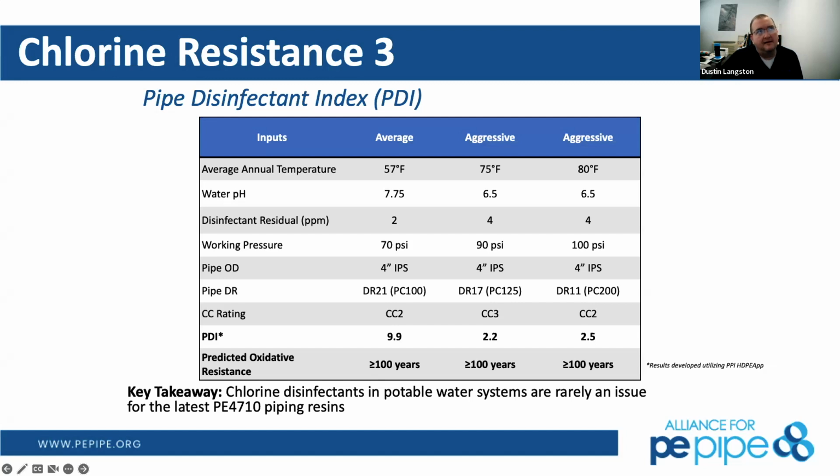So about 5-8 years ago, we were having tubing size failures from high temperature and high chlorine concentrations in the Southwest desert. So Tucson, Arizona, Las Vegas, Nevada, and all of these were on tubing for water service sizes. Mostly 1-inch DR11, 3/4-inch DR11, very thin pipe walls. And we were seeing these failures as soon as 15 to 25 years after installation. And looking at those failures and what the failure method was, which was ultimately sped up slow crack growth, we figured out a way to design for it.